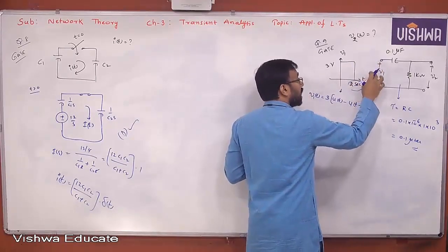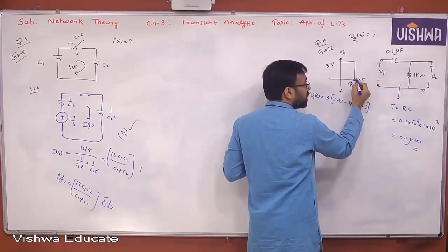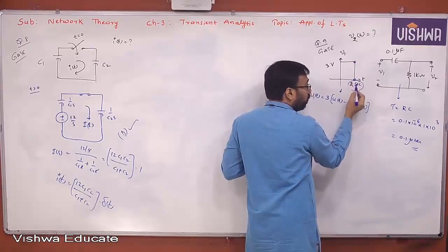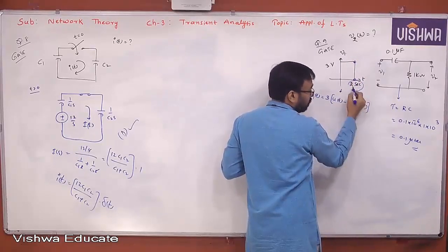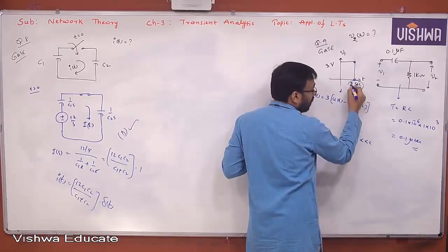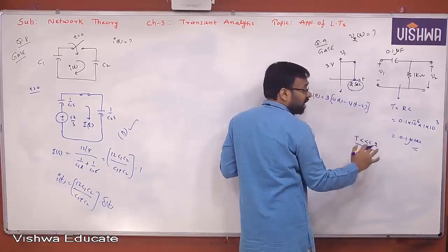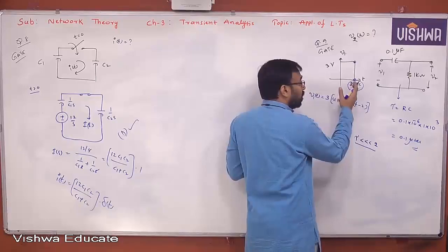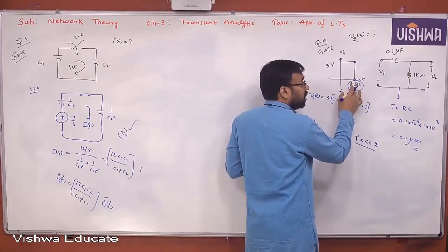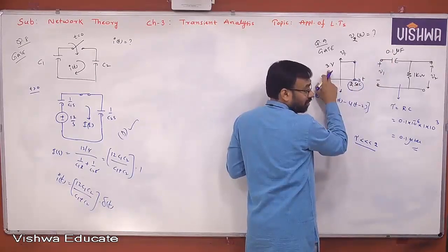That means the voltage across this network is given up to 2 seconds. At 2 seconds, instantaneously, the value of this V1 is coming down to 0. Now you compare this tau and the time. When you compare, tau is very much less than the duration of this particular pulse, that is 2 seconds. It is clearly understood that much in advance to this 2 seconds itself, the capacitor got charged to the full voltage or not? Yes or no, all of you?